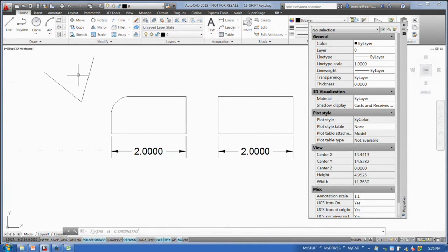Very good, all right, we got one. They were louder than you guys, though. So the right-hand side of the room's doing better. Holding the Shift key down overrides any current radius, just for that command. Yes, same thing with chamfer.